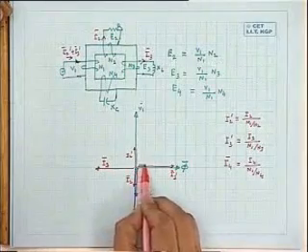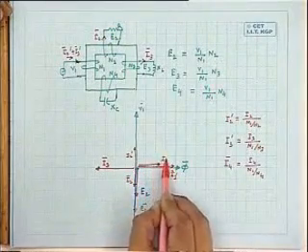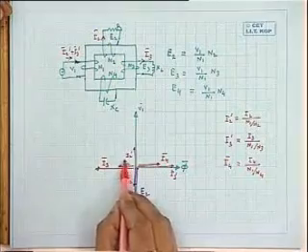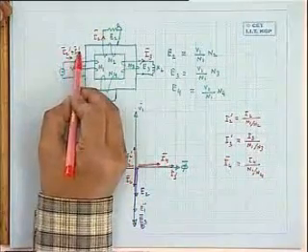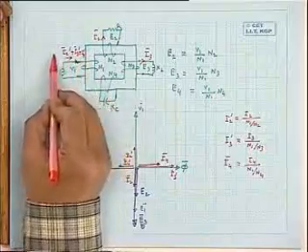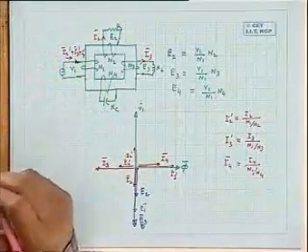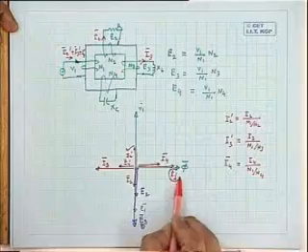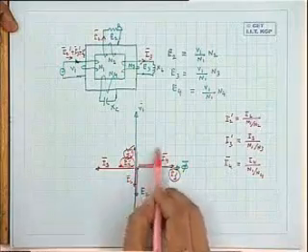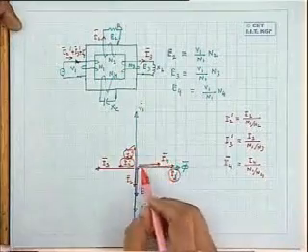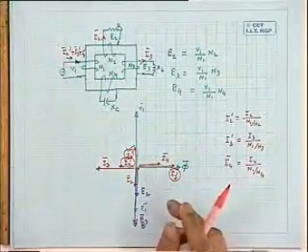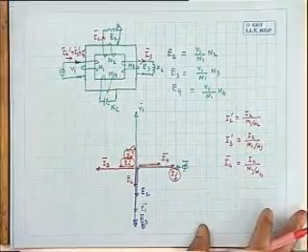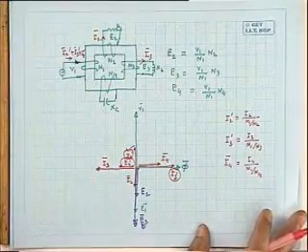Suppose this is I3 dashed. And I4 will be here, leading the voltage E4 dashed. And I4 dashed will be perhaps here. So I2 dashed plus I3 dashed plus I4 dashed will now decide the total current drawn from the supply. So the vector addition of I2 dashed, I3 dashed and I4 dashed will give you the resultant current, and you can find it out. So the MMF balance of the several windings will ultimately give you the current in the primary winding.